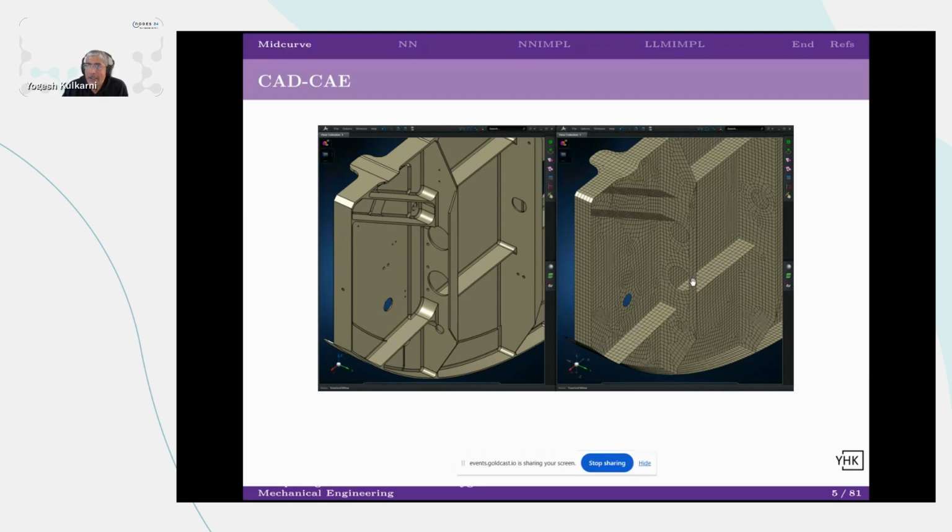If you can see clearly, when the shape is like this, thickness is constant, the elements are brick elements, meaning solid brick elements. But in the case of sheet metal, as I said, or plastic, where thickness is constant, what you do is create a surface between the thickness, okay, and do surface meshing on it. Meaning instead of 3D brick meshing, you do surface meshing. What's the advantage? I'll show you the advantage.